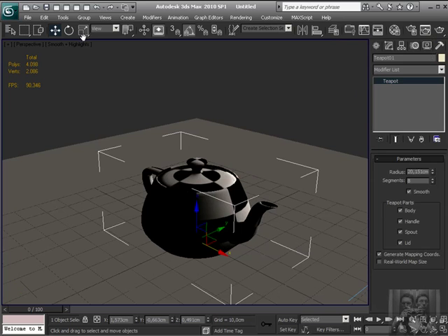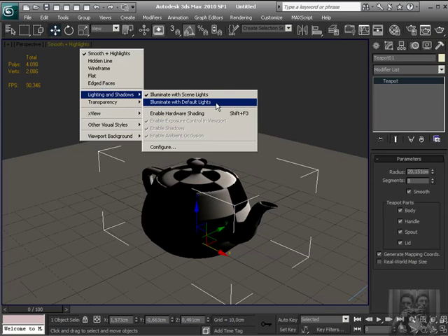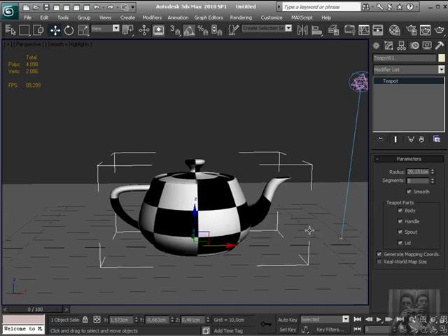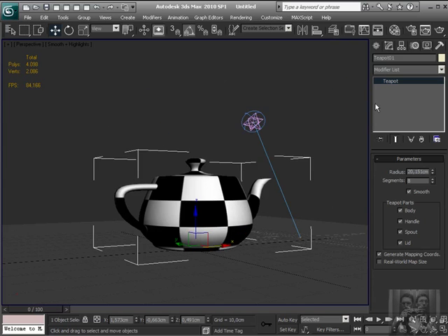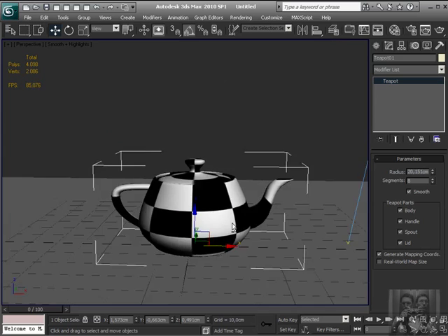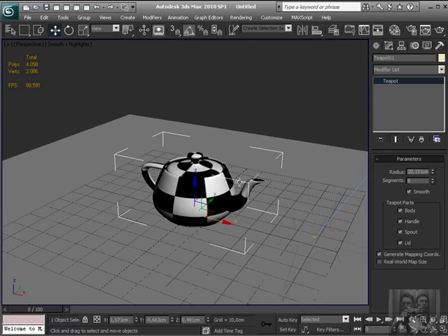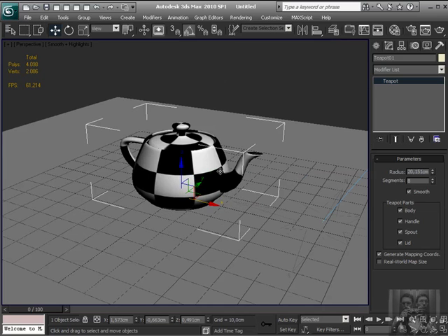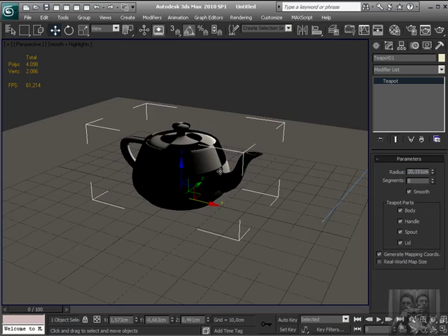You can choose to enable this operation and use the default without shadow, without illumination, with variation from the color, and you can see a good light on all objects. There is a little shortcut for this. For example, you can press Ctrl and L. You can see it is very good.